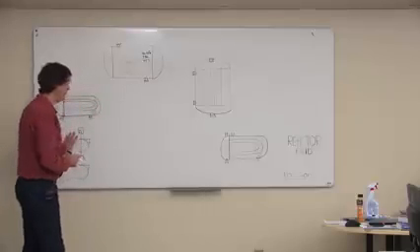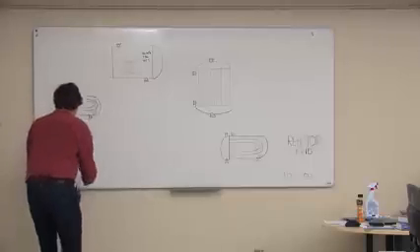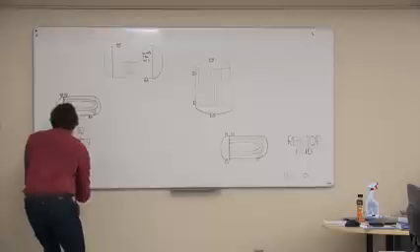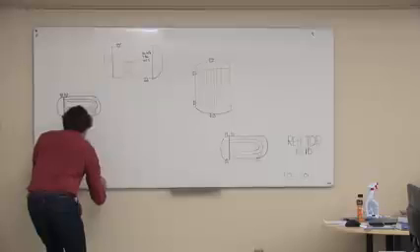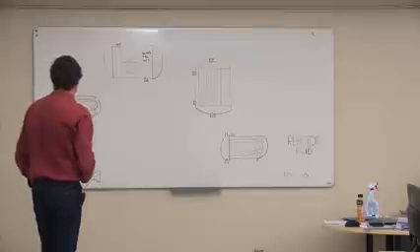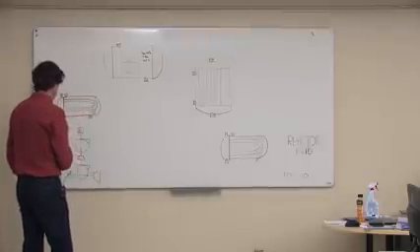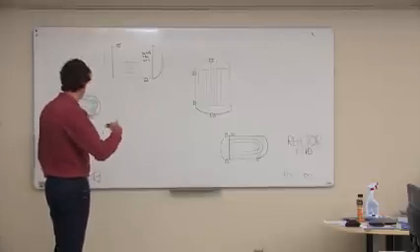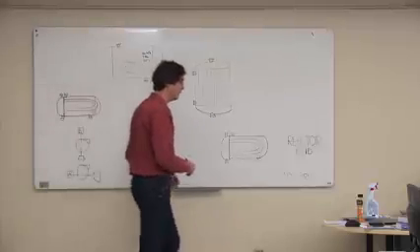So we could get away maybe with putting a steam turbine just on one pump, but it might not be the best idea to do that. We might want to have a motor and a steam turbine on both pumps. The reason you're going to have two pumps probably is you want to do maintenance on the pumps on a regular basis, and so you want to be able to flip those pumps back and forth, start one and run the other. I might rotate those motors and things like that.